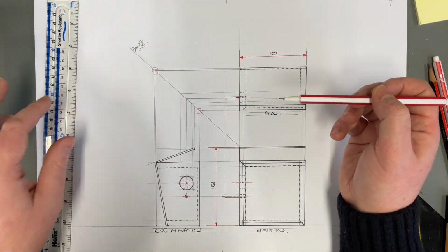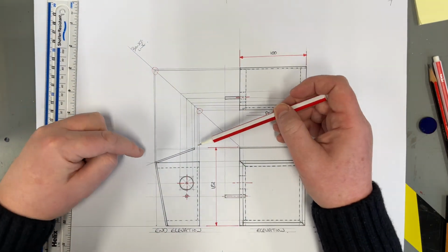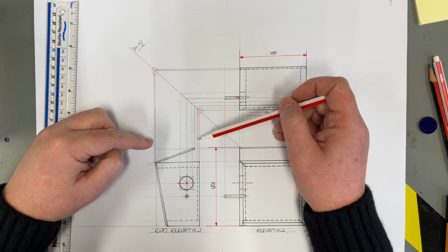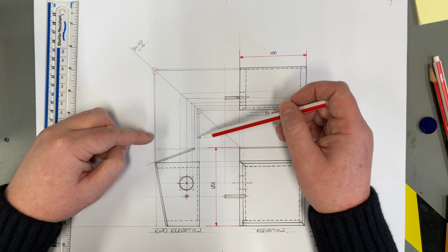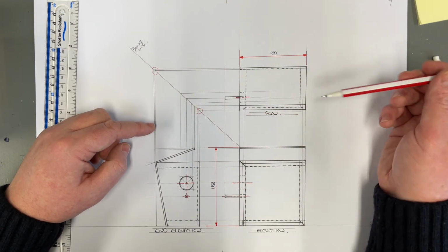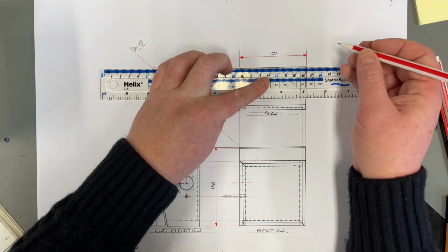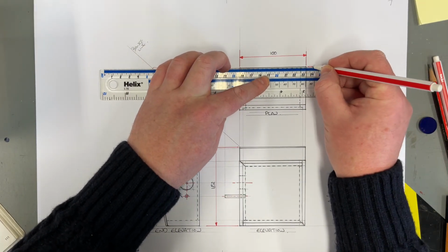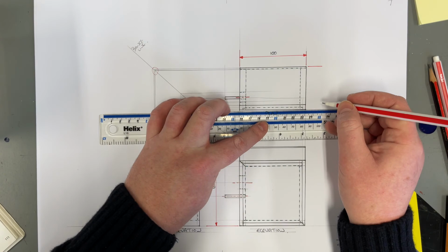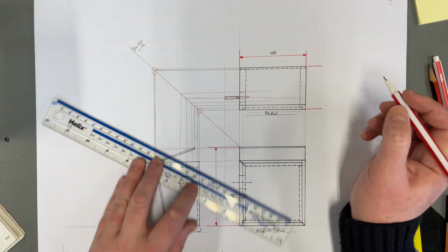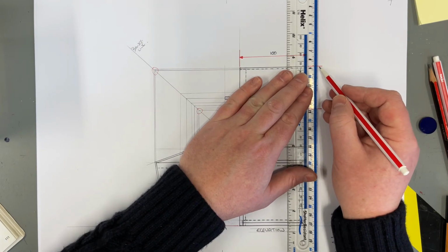And we'll do exactly the same thing for breadth. Now, breadth in this instance could be a wee bit messy. If we put breadth above the end elevation here, we are going to be able to see it and understand it, but there's so many construction lines going on here just now that we might actually be better sticking the breadth over here where we have more room. So from the back of the shape, a leader line that doesn't touch front of the shape, leader line and dimension line.